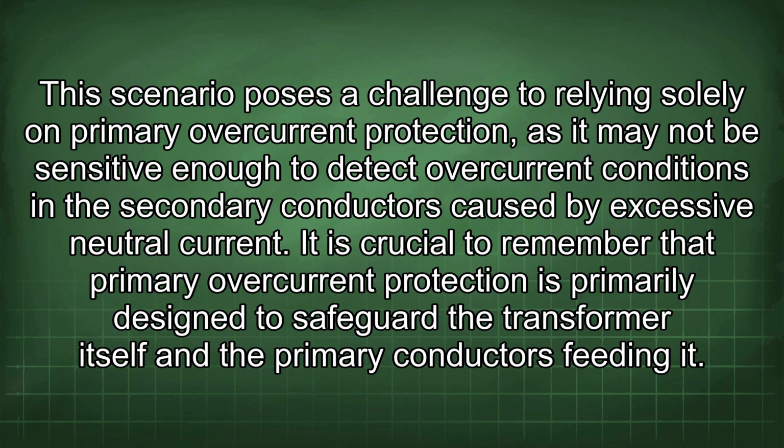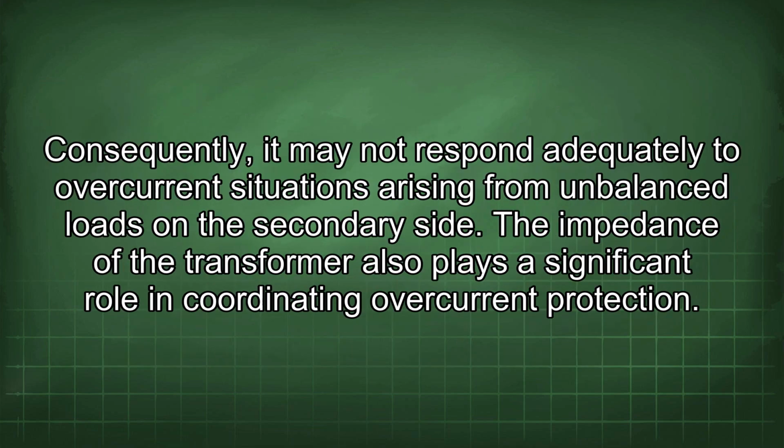It is crucial to remember that primary overcurrent protection is primarily designed to safeguard the transformer itself and the primary conductors feeding it. Consequently, it may not respond adequately to overcurrent situations arising from unbalanced loads on the secondary side.